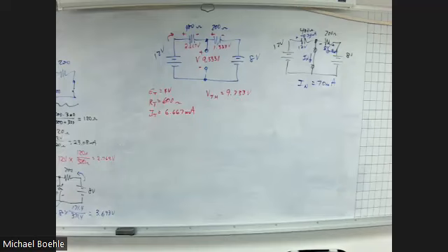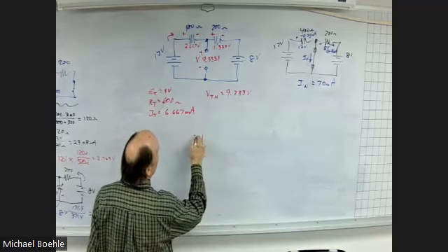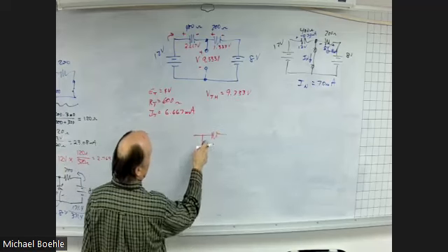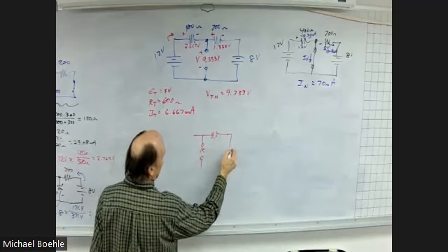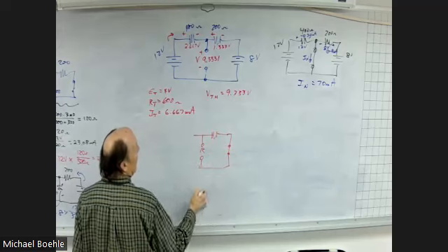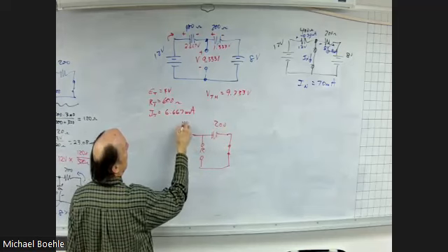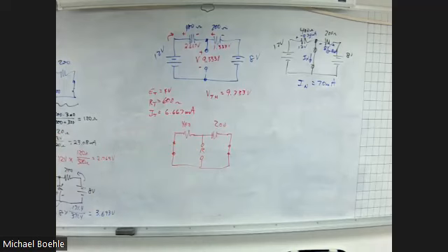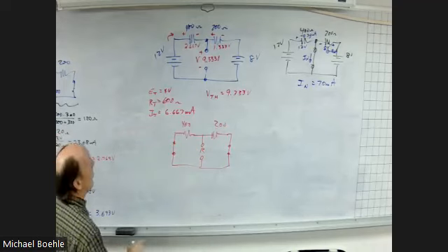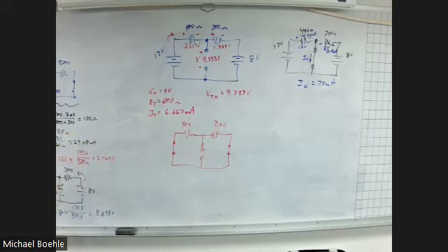Now, I can actually use those two numbers to find the Norton and Thevenin resistance, but let's just show you how you do it. So to find the resistance, I basically remove the component and I look for the resistance between those 2 points, replacing all the sources with their ideal internal resistance, which, since they're both voltage sources, are shorts. So now as a result, the 400 and the 200 ohm resistor are in parallel, right?